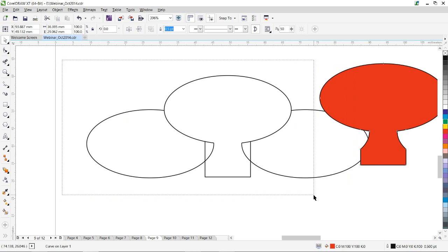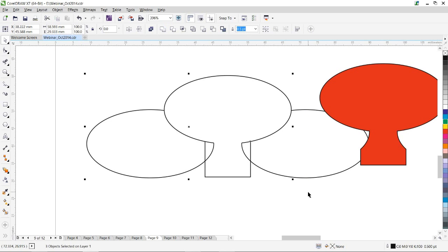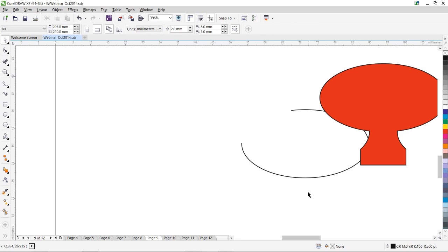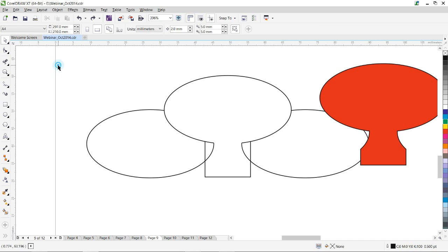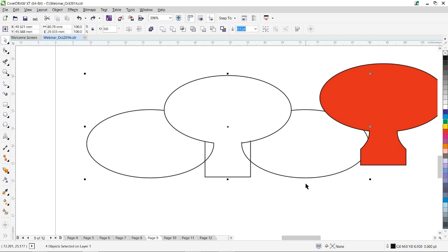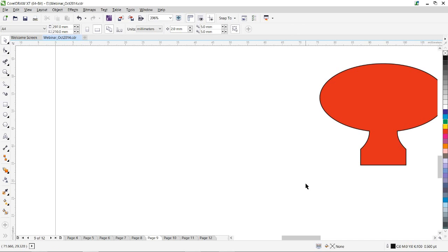So rest all. Okay, now if I am selecting this, this is another feature with modifier key feature, I should say. If I am selecting this, only this much is selected and this part is left. Why this happens is, when I am dragging this, all the objects that are inside the marquee selection are selected. When I want all the objects that are even touching my marquee selection, I just have to press the Alt key. So everything is removed now.